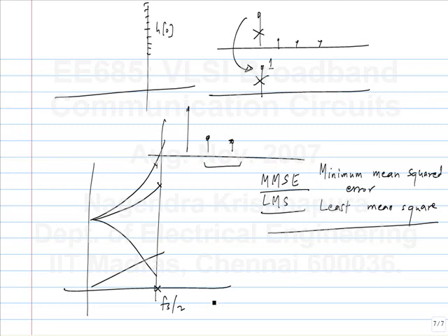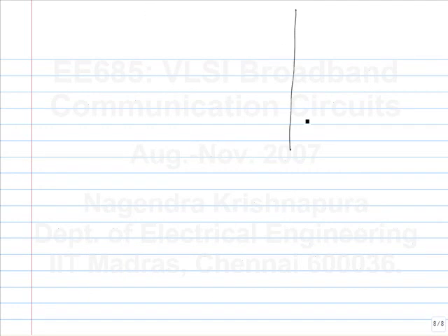So we are only concerned with frequencies from 0 to fs by 2. When we talk about discrete time stuff, it's not because of any low frequency limitation or something. The repetition of the spectrum is inherent to sampling. Any questions on that?